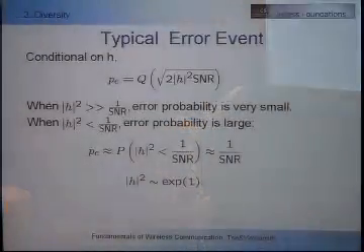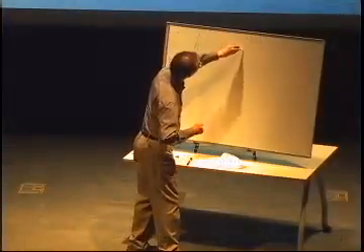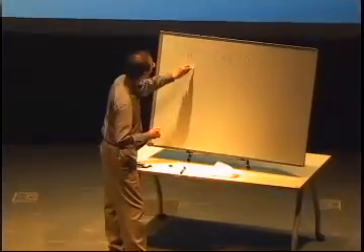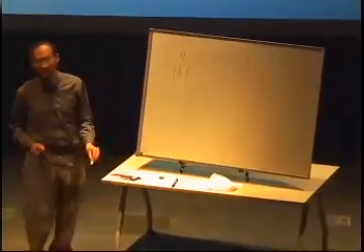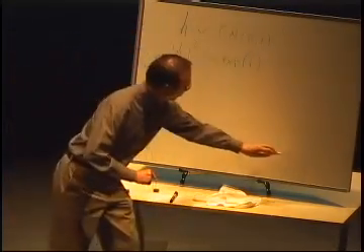That is this event. And this probability, unfortunately, is very high. It's only of the order of 1 over SNR. Okay? So why is that? Let's plot something here. So h is a Rayleigh fading random variable. So h is CN(0,1). So you can compute the PDF of h squared. That's just an exercise. This is exponential with mean 1. Okay? So I plot the PDF.